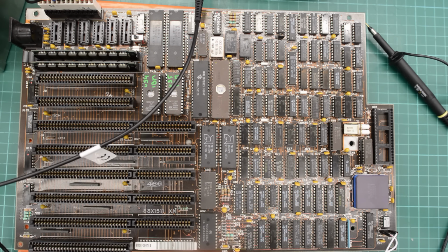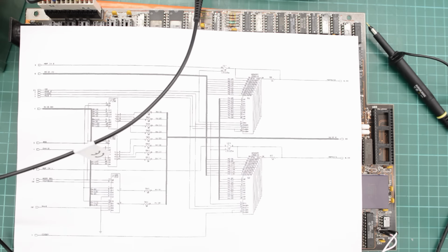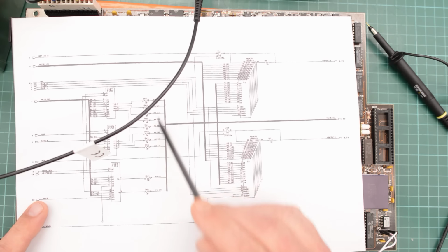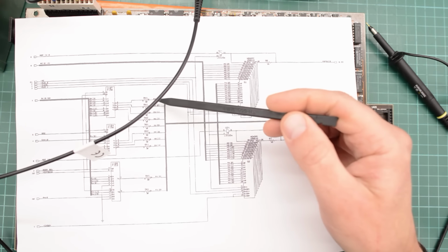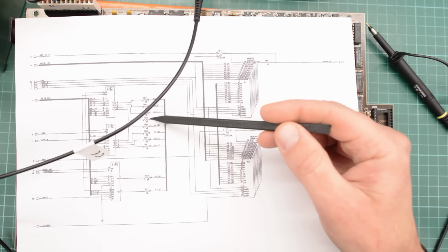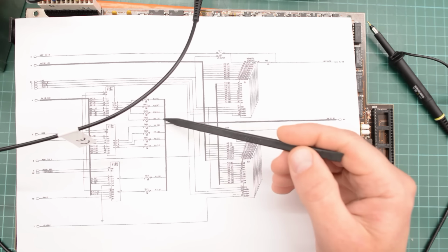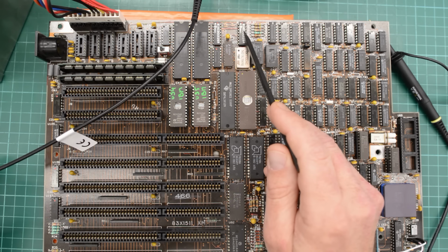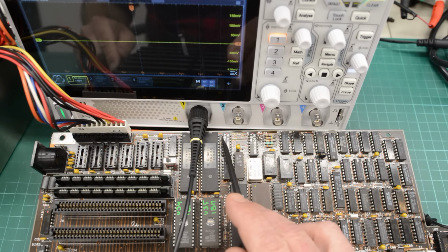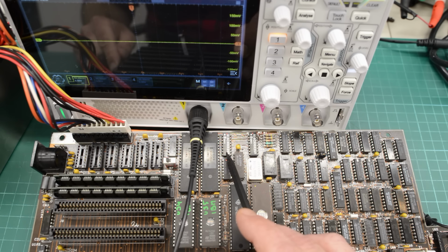They are of course accessible underneath the board, but they're not labeled, so that would be a pretty hefty task to figure out which pin is which. So instead we could scope the signals at this resistor pack here. Same thing here, it's really hard to read, but I think it says AN1 and AN2. I can read some of the pin numbers. And here are our resistor packs. I think this is the best I can do. So these resistor packs are just straight through resistors. From pin 1 all the way down here to whatever pin this is.